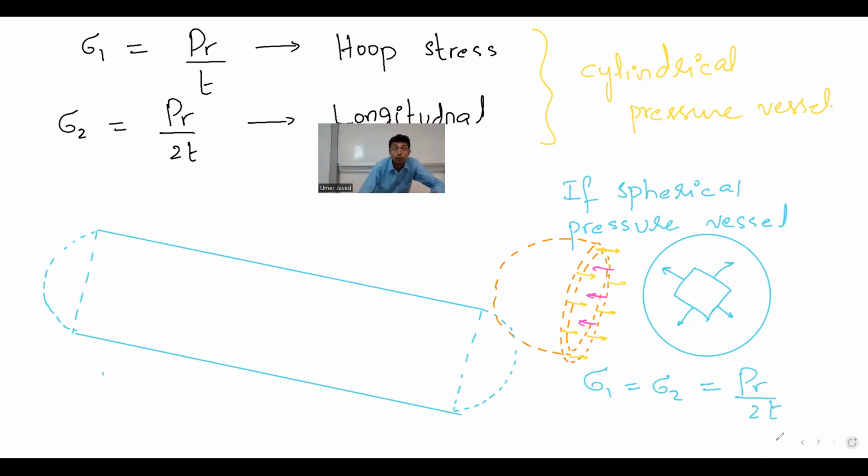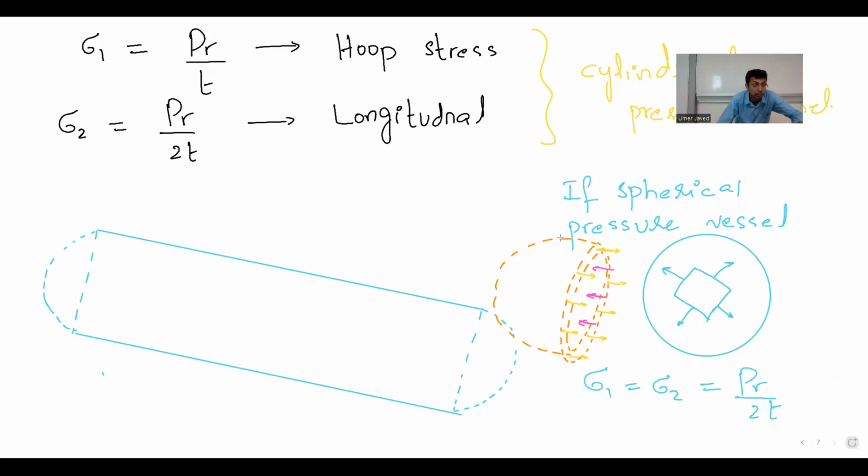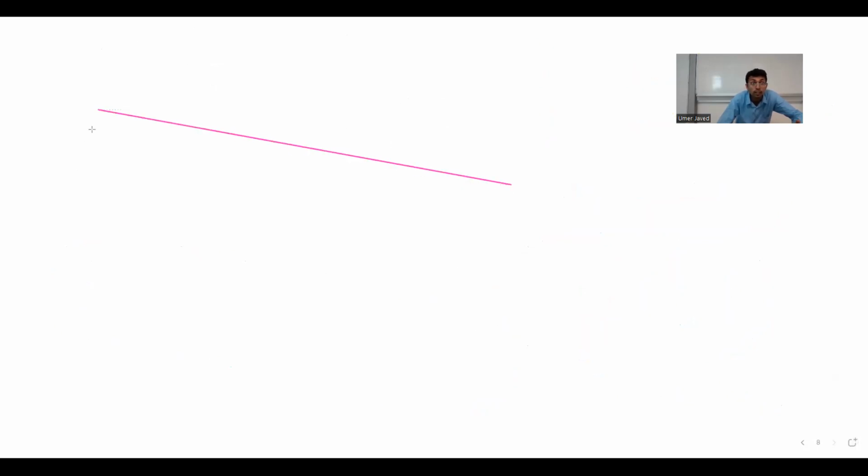And before you go, why don't you do a problem? Is this clear or not? Now, am I talking about a thick pressure vessel or thin pressure vessel? Thick or thin right now? Anyone? Thin, like a Coca-Cola can, okay? If you have a thick pressure vessel, then the analysis is not as easy as this one, because then the stress will vary along the thickness as well.